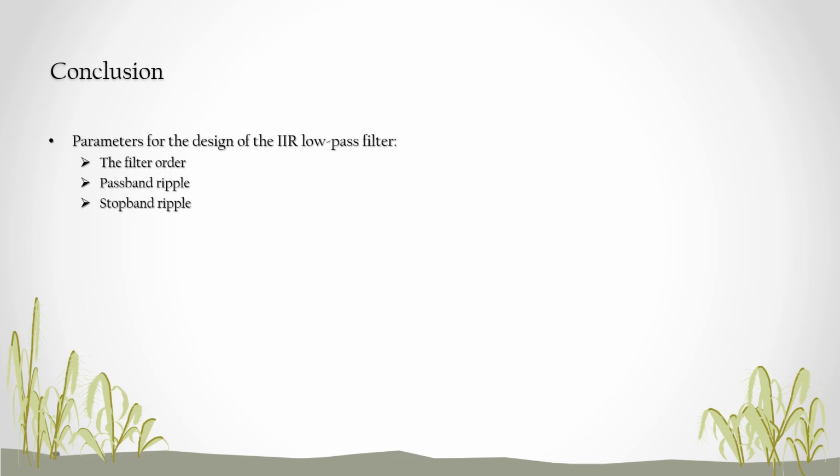The Butterworth filter was found to be the best compromise, considering only attenuation of the signal. It has no ripple in the passband or the stopband. However, this characteristic is usually used only when the filtering requirement is not demanding. Otherwise, it's not effective, and it's a high price to pay for the relatively poor performance.